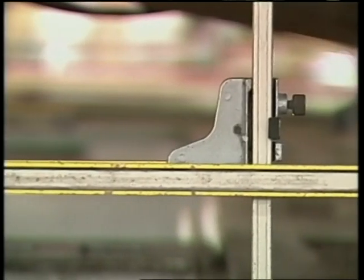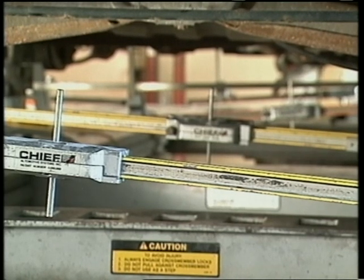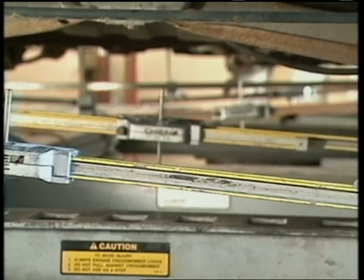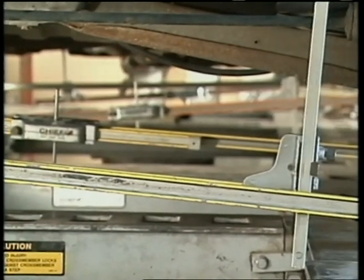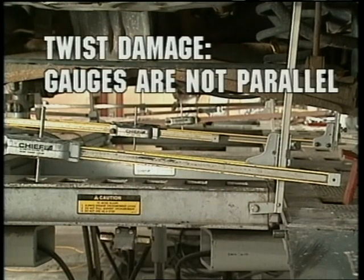Also, look across the full width of the car to see if the gauges are parallel. The first damage condition to look for is twist. Twist exists when one side of the vehicle is pushed low or high on one end and moves in the opposite direction on the other end. It's the last condition to occur and should be the first measured. If twist damage is present, the gauges will not be parallel.